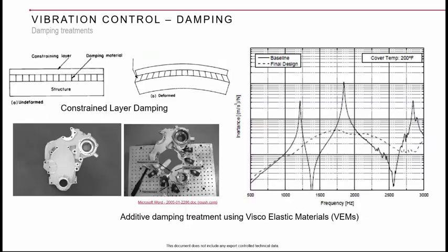So what exactly is it, if you see. This is your base structure. For example, you take this engine case, some automotive engine case, crankcase. Then you have the viscoelastic material that is attached here. This is a constrained layer damper here.